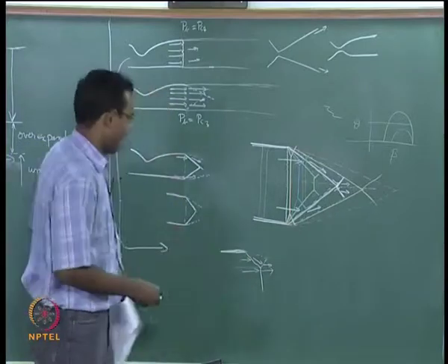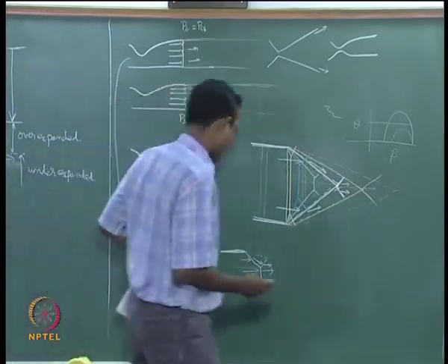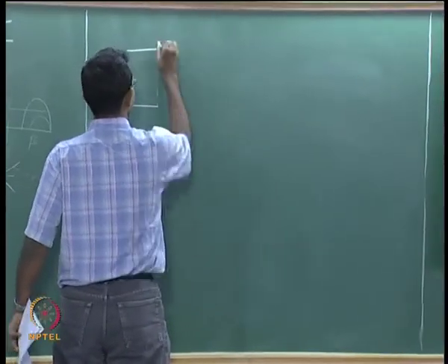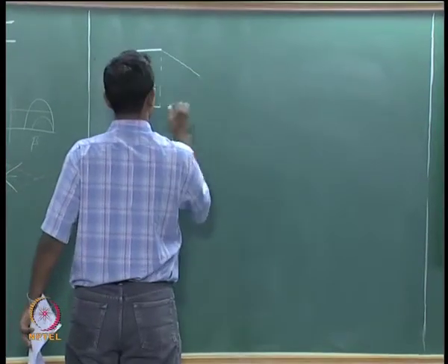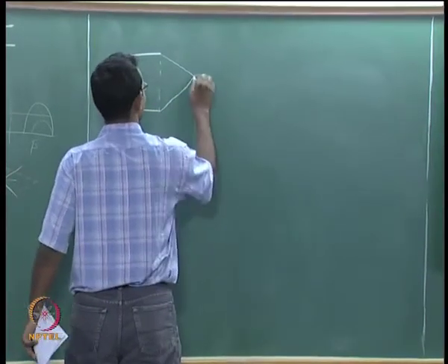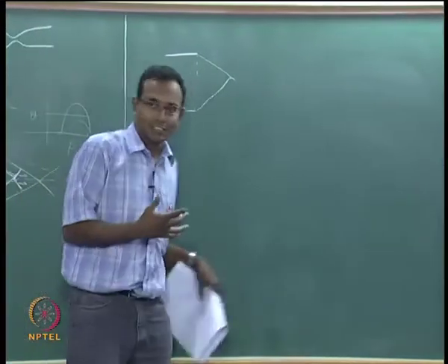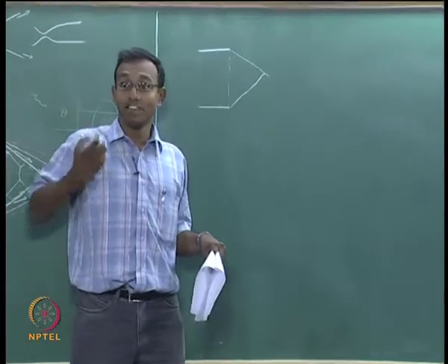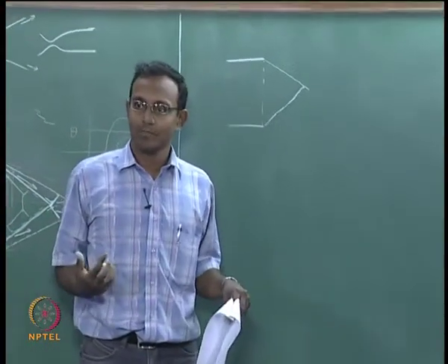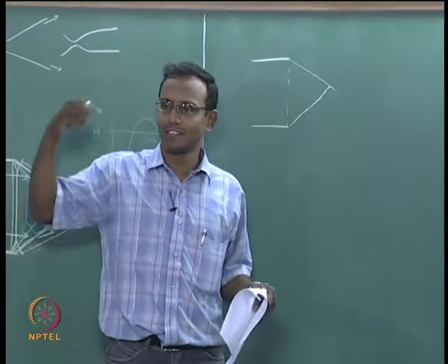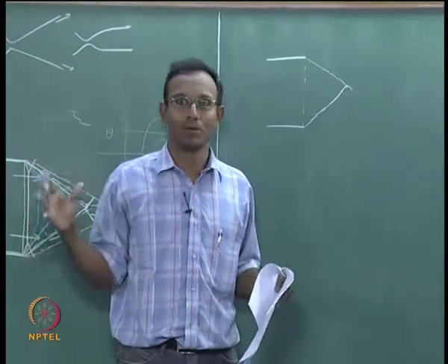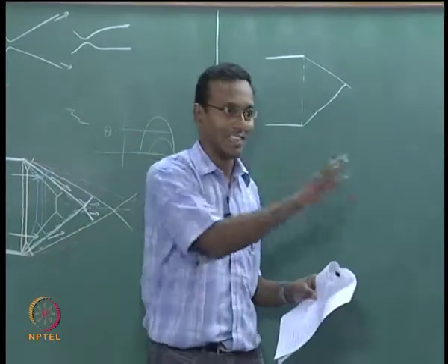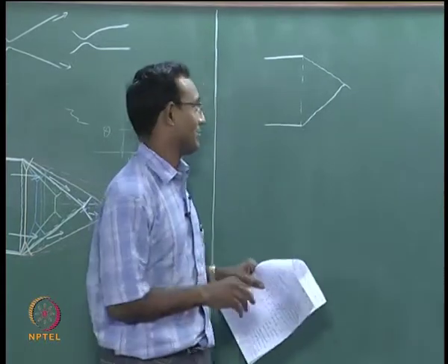Okay. So when I look at that, the way I want to look at it is I will take a simpler case where this is my exit plane and there is an oblique shock, there is another oblique shock, and I want to think about it as each of these shocks being some wave which is carrying a message, right. This is how we did it in 1D moving shock problems. We said if I suddenly close a door at the end of the pipe, the shock travels telling the pipe is closed, that kind of thing.